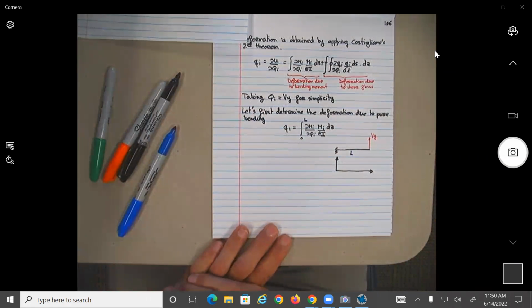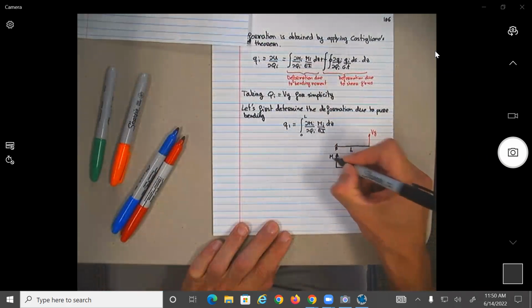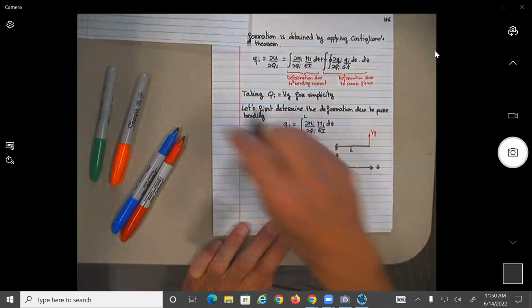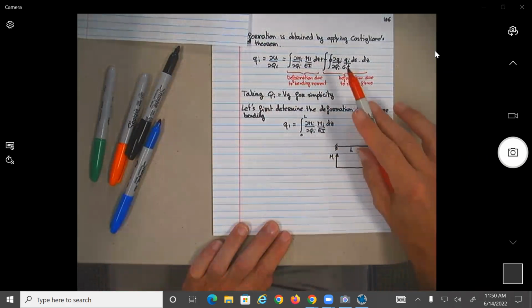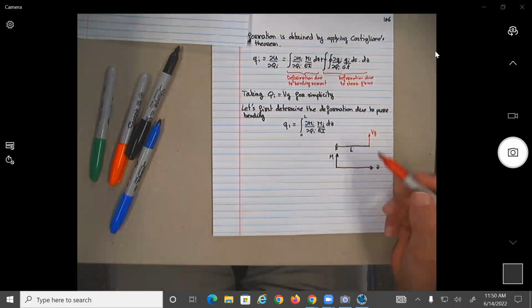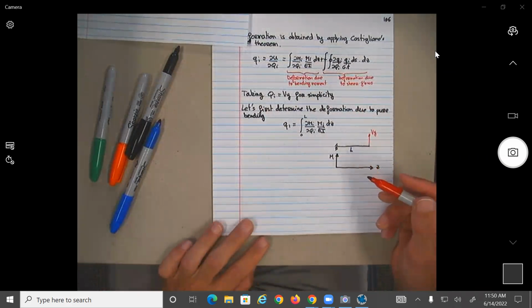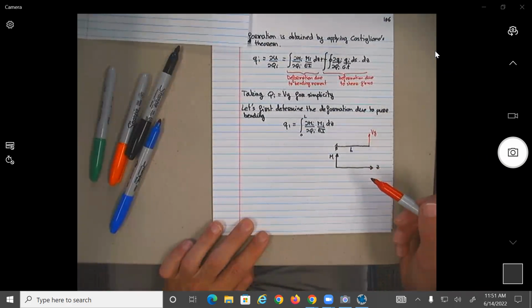If you had to do the free body diagram for the moment, what would that be? This is pushing up, so the reactive moment is going to go down, so really it should start from the negative value. It's not going to matter. What would be the maximum moment, at the tip or the root?